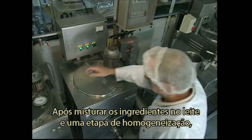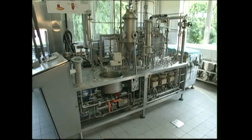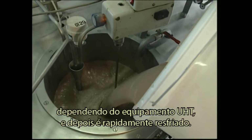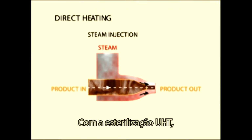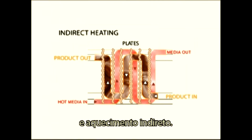After mixing the ingredients in the milk and a homogenization step, the chocolate milk is sterilized at 140 degrees Celsius for a few seconds, depending on the UHT equipment, and then quickly cooled. With UHT sterilization, there's a difference between direct heating and indirect heating.